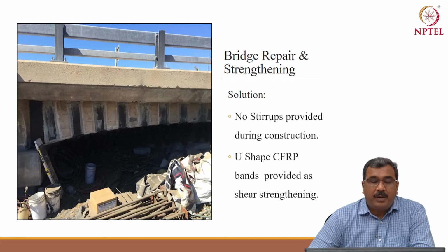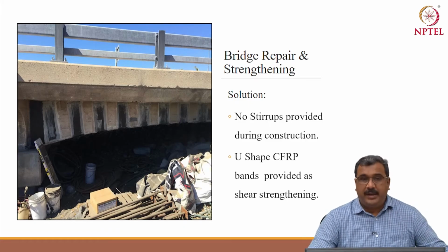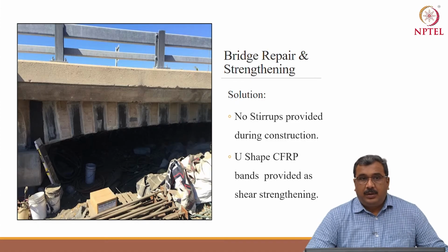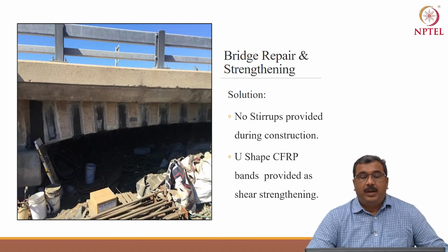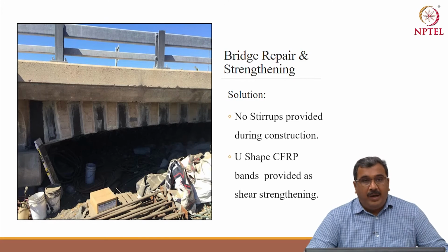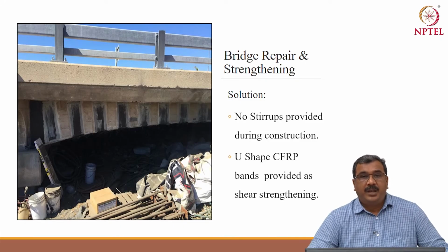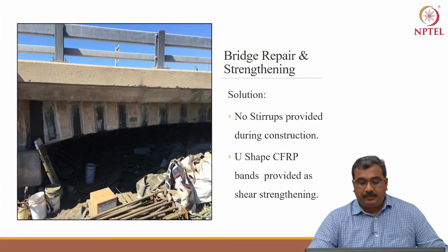That amount of carbon has been installed in the form of a wrap on 3 sides. Structural analysis has been carried out based on prevailing codes, and design calculation for CFRP has been carried out based on ACI 440.2R-2017.